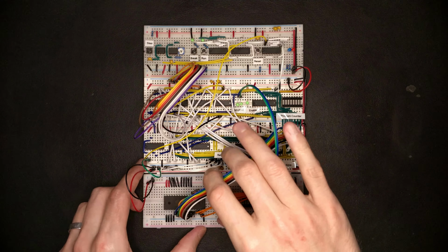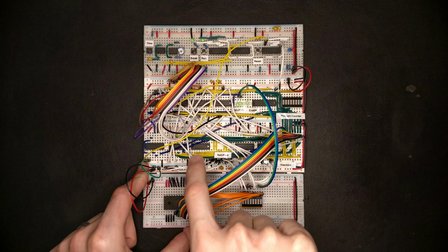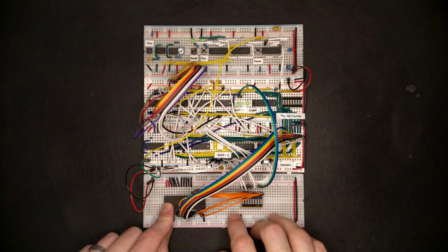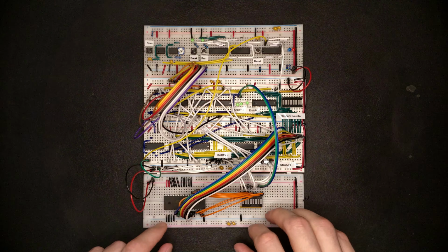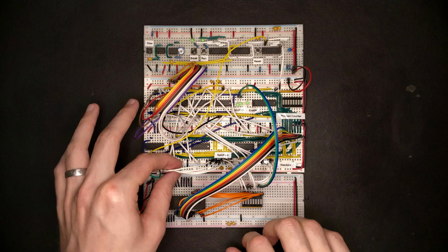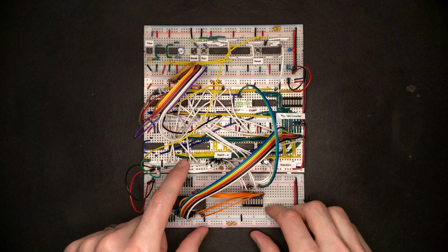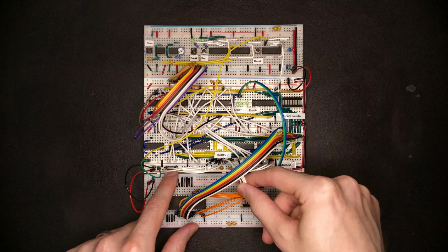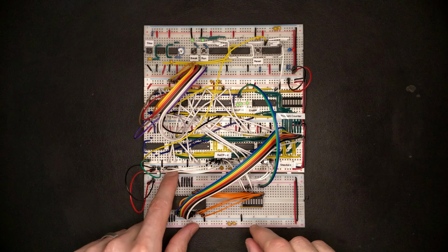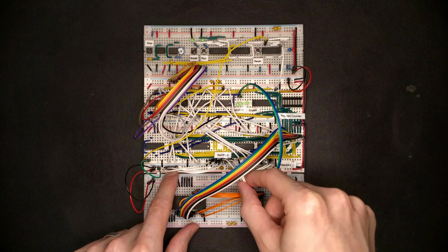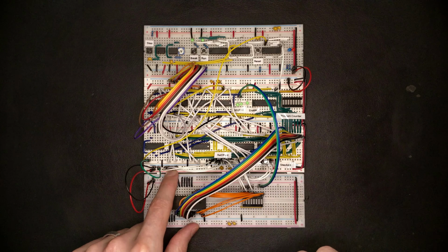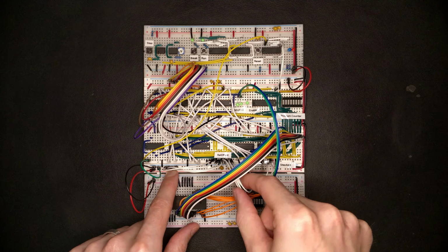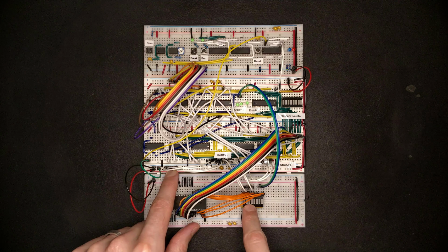What we need to think about is what we actually do with the upper 4 bits of the relative jump offset, which we don't have any bits at the moment from memory that we can use there. Since it's a relative jump offset and we've been dealing with 2's complement numbers earlier, where we want to represent negative numbers, a good thing to do instead of tying them to 0, which is called 0 extending, just adding zeros at the top, is to sign extend these 4 bits, which means that all the upper bits get connected to the topmost bit of whatever comes out of memory. This has the interesting effect that we are able to represent negative numbers as well.